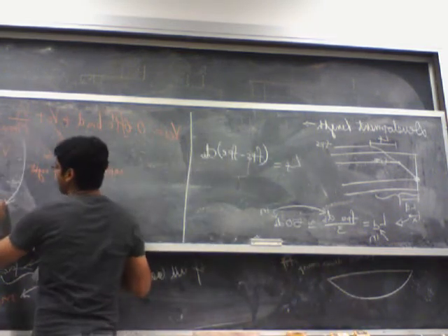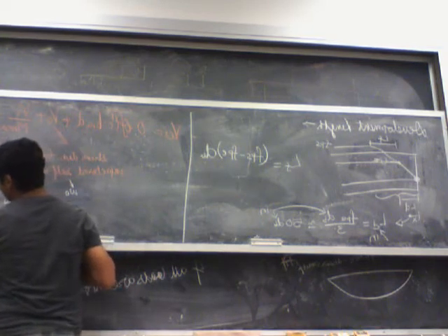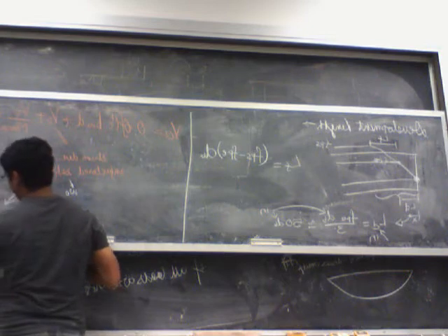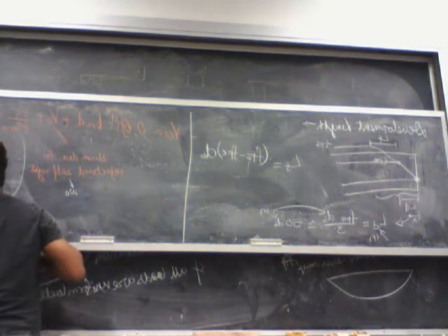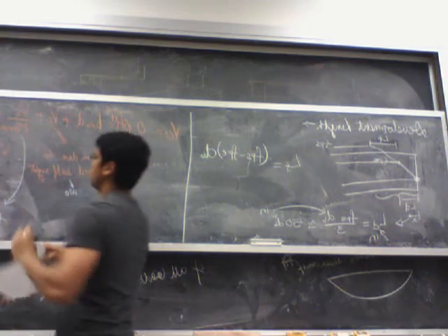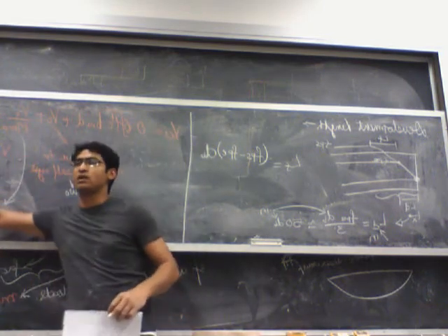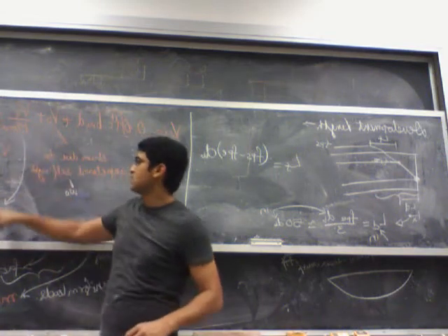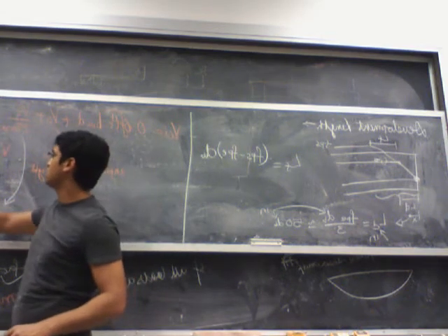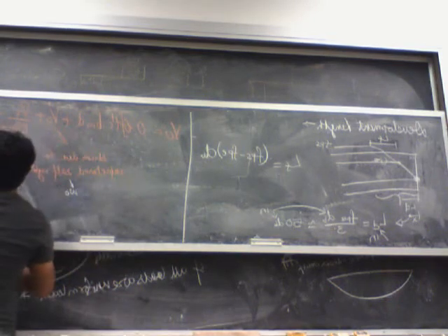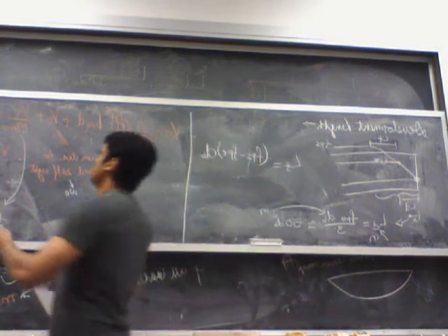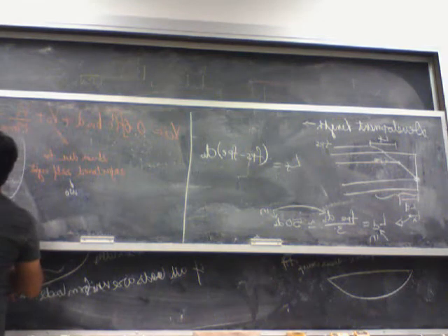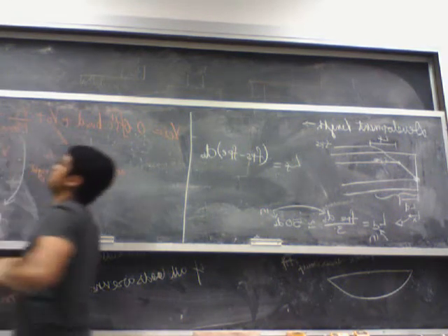Similarly, this M_max is the moment due to this same load. So V_i is the shear due to these factored loads except the self weight. M_max is the moment due to the same loads without the self weight. And this M_cre is defined as the cracking moment minus the moment due to the self weight. So this is actually M_cr minus the moment due to the self weight.